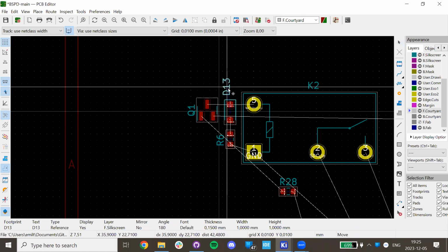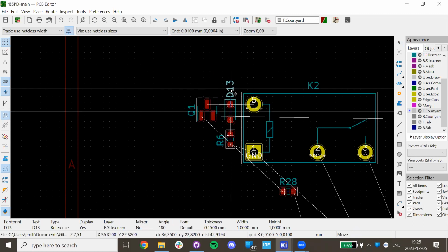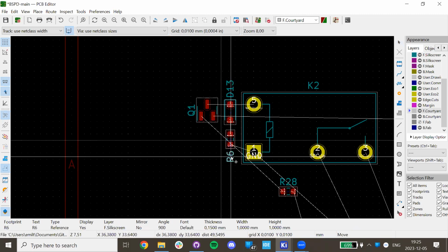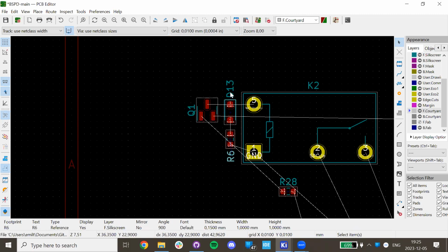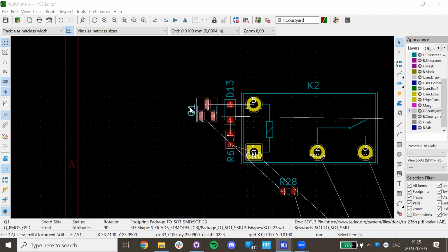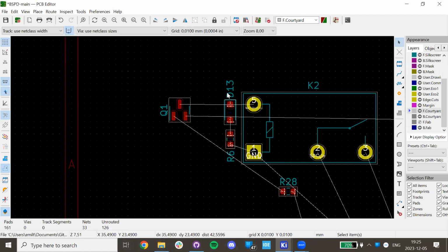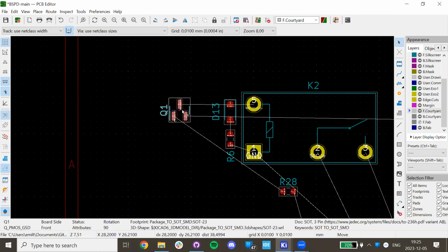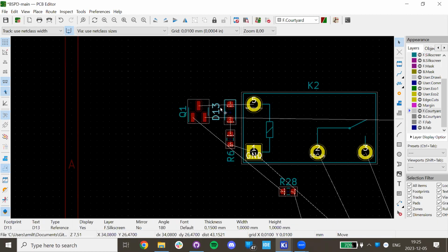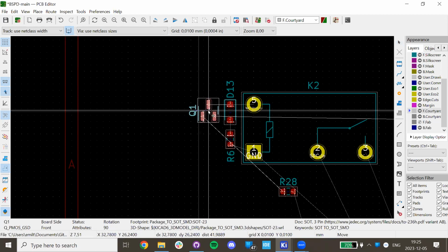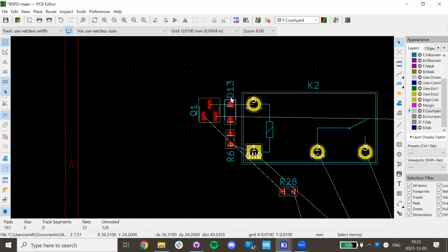These numbers, or reference designators I think they're called, are primarily here on the silk screen to help you when soldering. So if you see that D16 is this one, I should place it close. Try to keep them if you can, but don't make your PCB larger because I need to, for example, have this D13 in between here. Like this. This is really stupid. Then just move it out of the way. And if you're making something really, really small, they might just be super annoying and don't fit. They just take a bunch of extra space. Then get rid of them completely. I'll show you a trick.